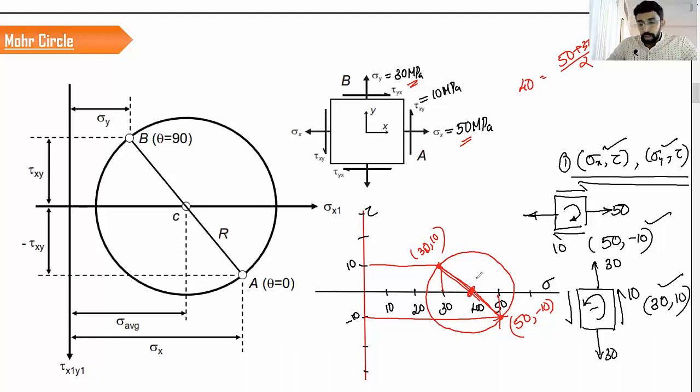Okay. Now, after completing the Mohr circle, certain things you should keep in your mind. First thing is that, once the Mohr circle is over, the diameter that we have joined right now is going to be the reference line that we are going to take, not the actual sigma axis. No, we are not going to use this axis anymore. So now to calculate anything related to the stress system, we need a reference line, and that reference line is going to be this diameter, and that is very important because you cannot measure anything from the actual x-axis. No, that is not the way we are going to do it. This is the way we are going to do it.